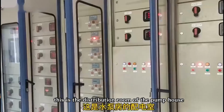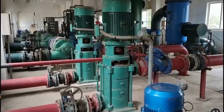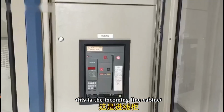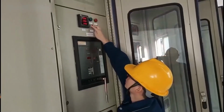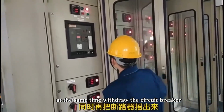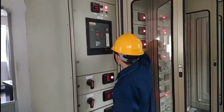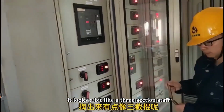This is the distribution room of the pump house. The equipment on site has been shut down, with no load left. This is the incoming line cabinet. Pressing the stop button can cut off the power. At the same time, withdraw the circuit breaker. The crank handle is hidden in this whole clever design. Pulling it out, it looks a bit like a 3-section staff.